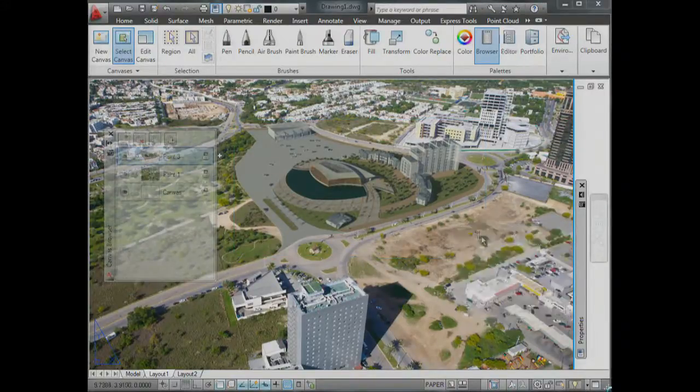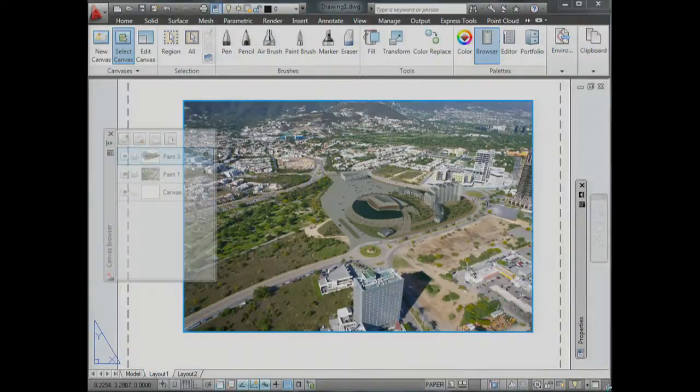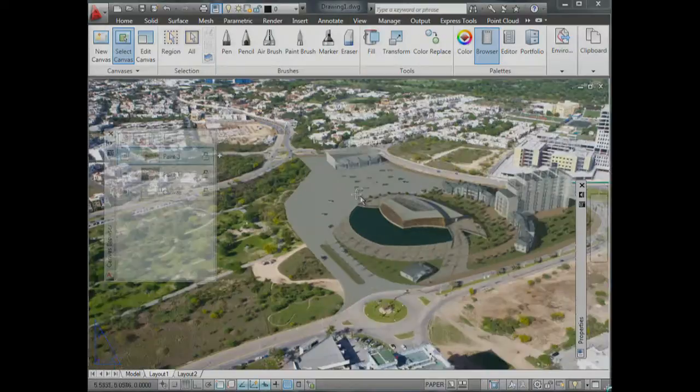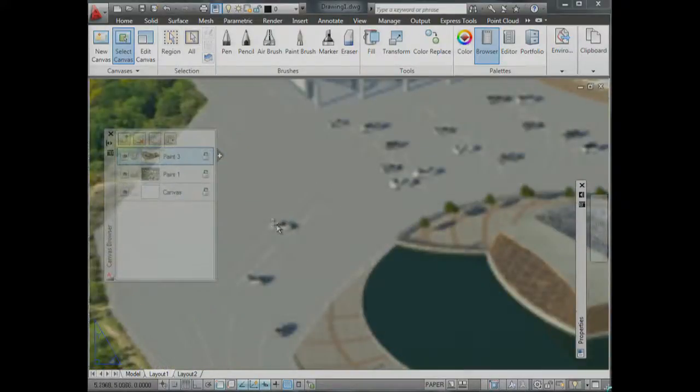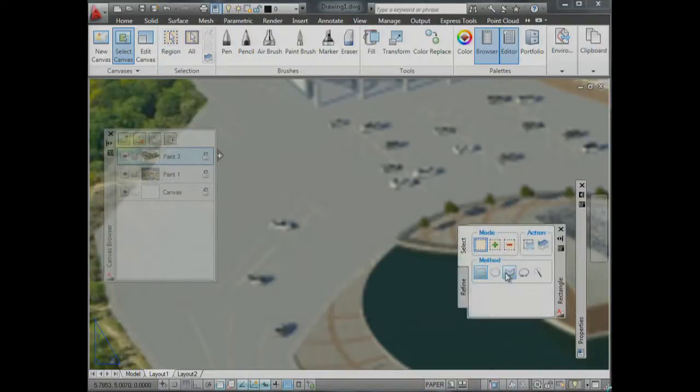The only thing I want to do now, just to show you another thing, is what happens if I need, for example, extra cars. I really don't want Marion to render more cars in the scene, right? So I'll just create a selection within her render. In this case, a polygonal selection, it could have been a lasso. You'll see that many of the options here are very familiar to anybody doing image editing software.